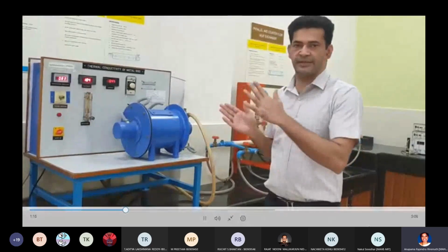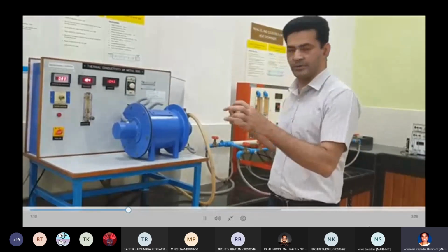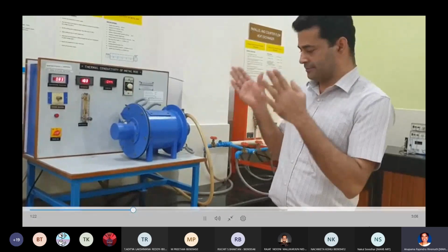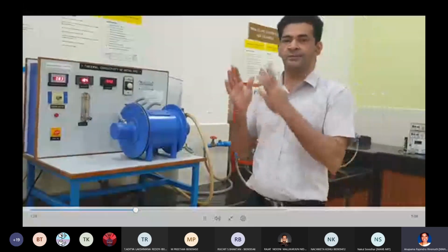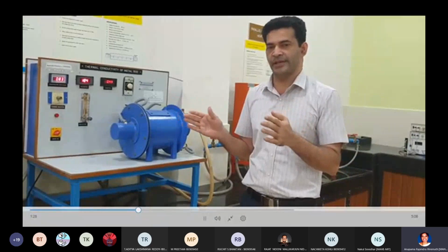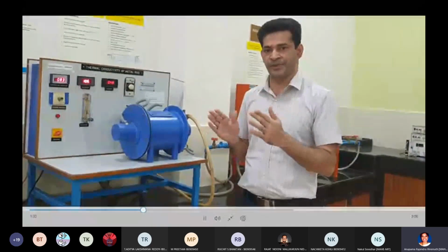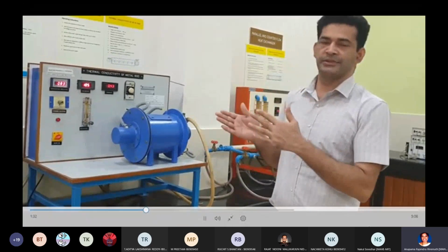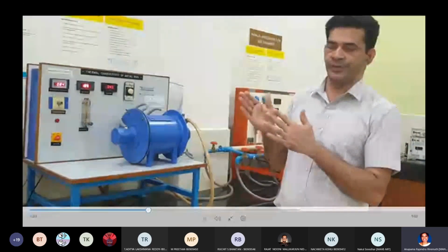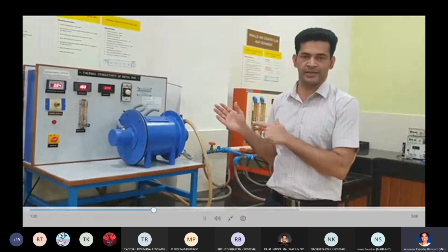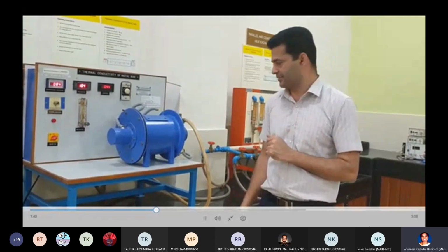So we can take a planar wall or a rod or a metal where we make the heat transfer along one direction, and if we know the temperature gradient and we know the area of cross section through which heat flows, and we can measure the rate of heat transfer, through that we can determine the thermal conductivity.